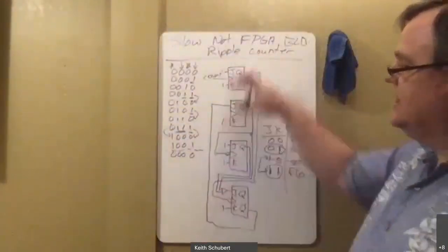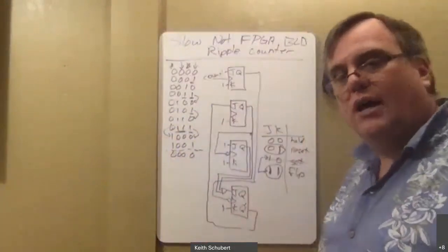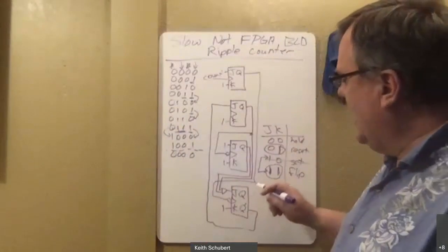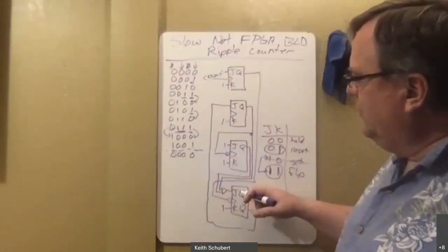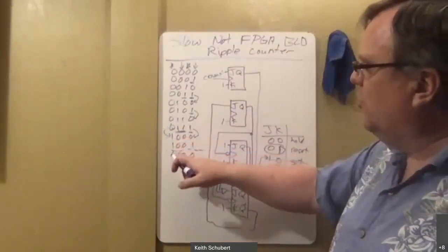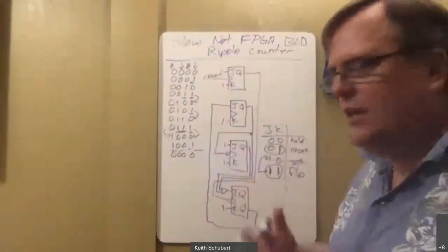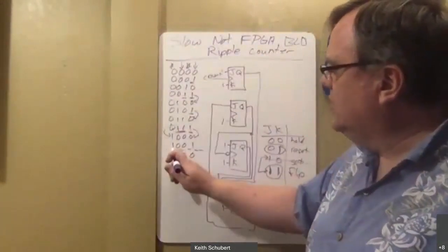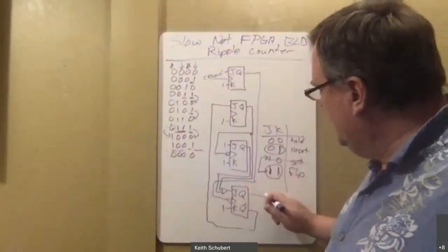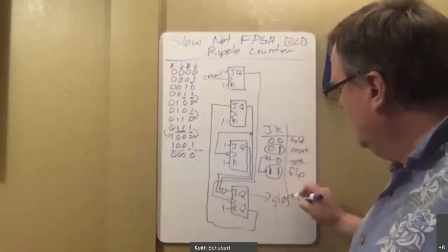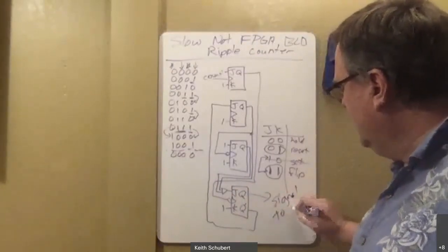And you can actually stack this. This makes 1 digit inside of your system. And I can take the output from this one. Whenever this last bit transitions from a 1 to a 0, I know my decade finished, so I should increment to the next one. So all I have to do is take this last bit. This is also the signal to the next bit.